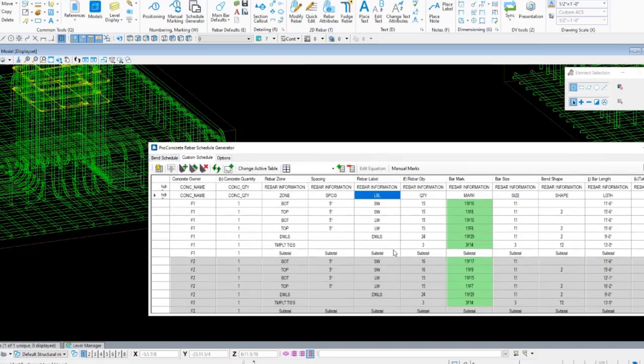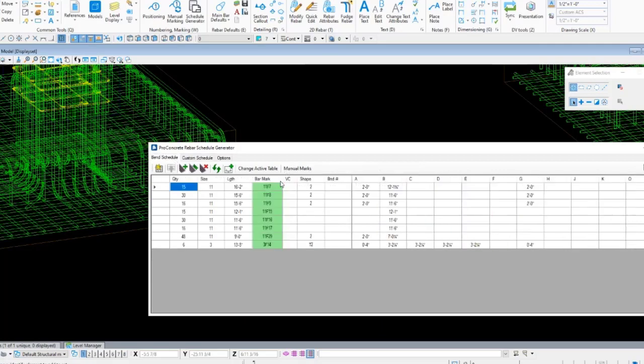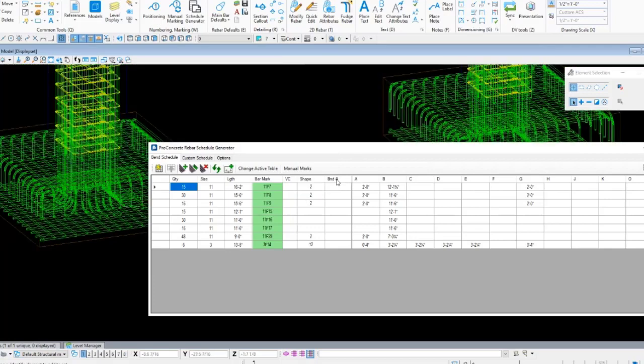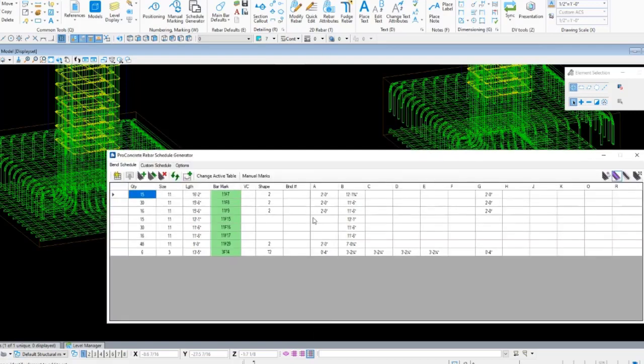Additionally, and it works for either table, the exclude or include. So if you wanted to exclude any column here, let's say the vary code, or maybe that bin number. If I were to place this table and none of my shapes that I have selected are going to make use of a numbered leg, like an A1 or a B1, that would make use of this bin number column, I could just choose to exclude it. And then I'm saving a little bit more white space on my drawing with this table.